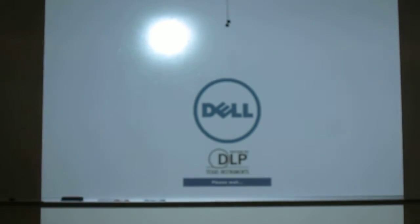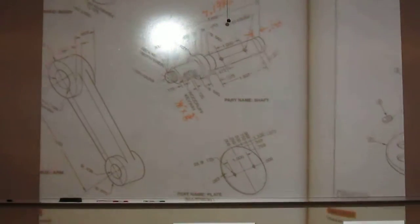There is a trick to this guy, and the only real trick, and it also aligns your Woodruff key, is that you're kind of slanted on where the butterfly valve goes. That's what I was wondering, because with the face of that, how that face is cut out like that for your plate, in reference to that, is your Woodruff key angled from that? Yeah, and let me show you how that is. It's 45 degrees.